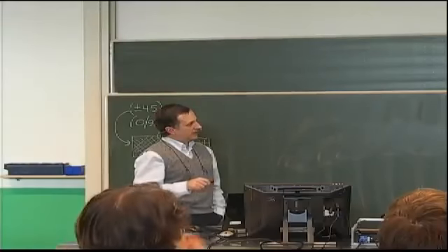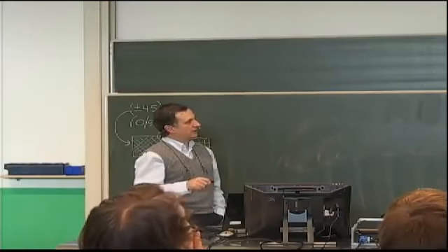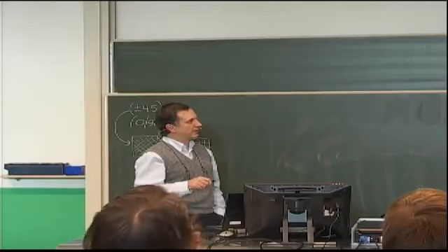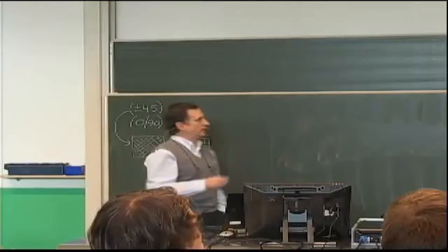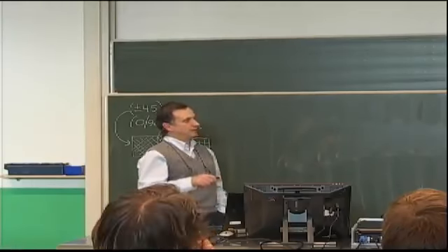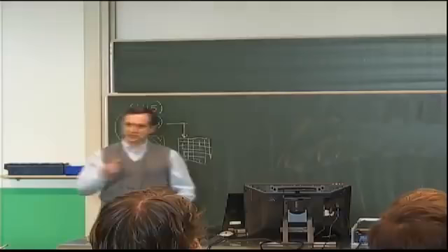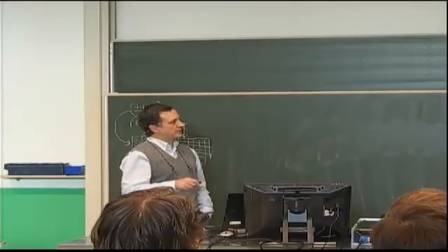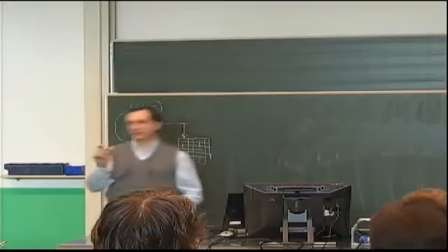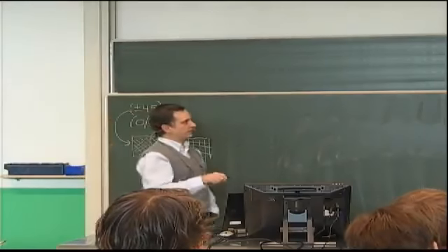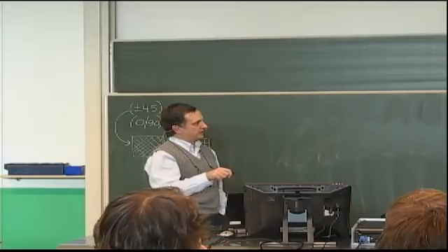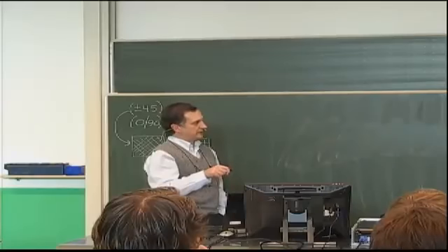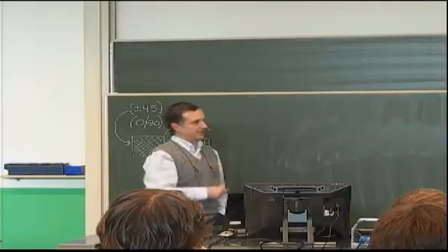Again, the sigma y stress is very close to 0 if y over b is less than 0.2 or so, or greater than 0.8. So there's again a region in the center of the plate which would require reinforcement to cover sigma y. Now you can see also at the same time that sigma y and tau xy do not necessarily correspond to the same region in the center in which they are appreciable. Tau xy was from 0.3 to about 0.6 or 0.7, while the sigma y is over a slightly larger region.